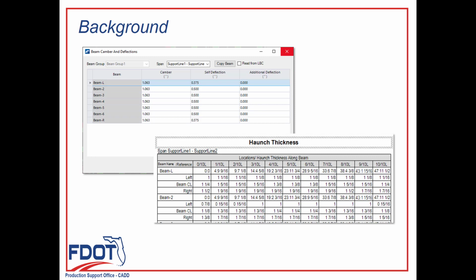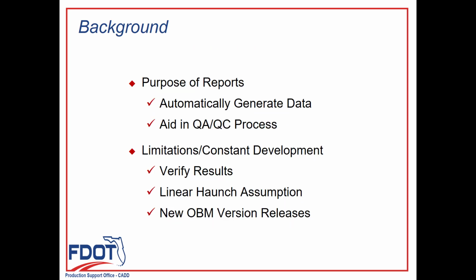Another thing to keep in mind is that the bearing seat elevation report tool, which provides the pedestal or grout pad and bevel plate elevations, does assume a level pedestal. So for beam grades between 0.5 and 2% for FDOT, where the beam seats are to be sloped, that would have to be accounted for outside of the program. All of these various report tools, in addition to the three main ones, will be touched on at the end